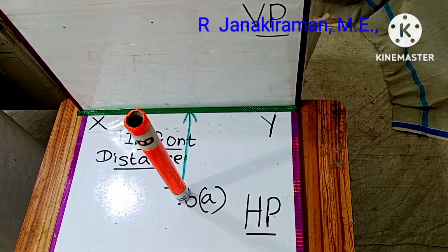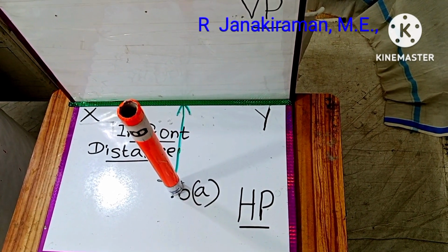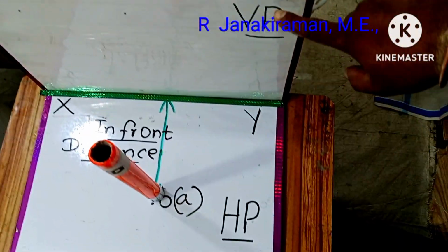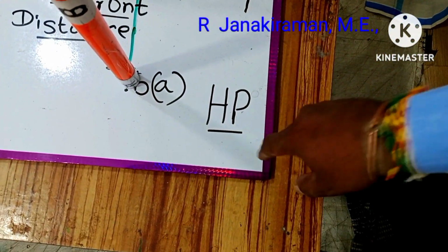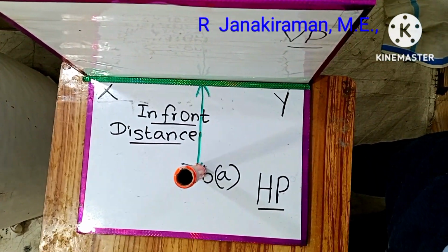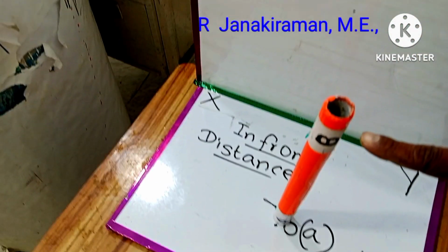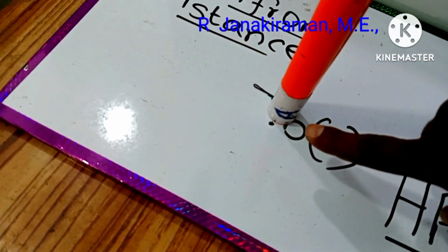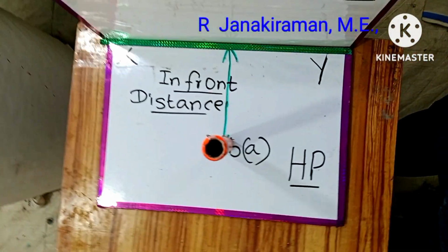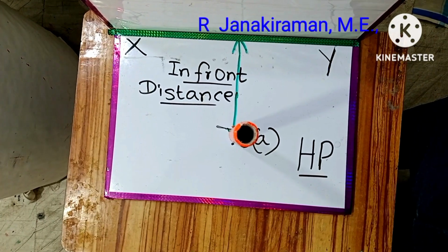Now I'm going to draw the top view. For explaining the projection of top view, now I turn the camera. So looking from the top, this is VP, vertical plane, and this is horizontal plane HP. Looking from the top, the observer can see the top view of the straight line perpendicular to HP and parallel to VP. So this is a top end point marked as B, bottom end point is marked as A. Okay, so looking from the top, the view projected is called a top view.